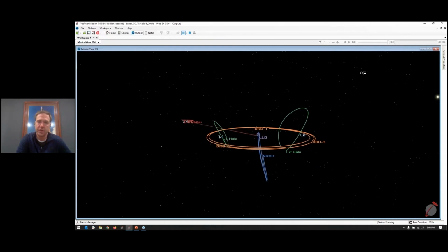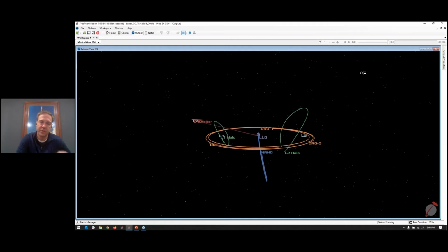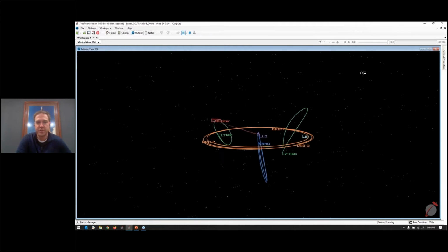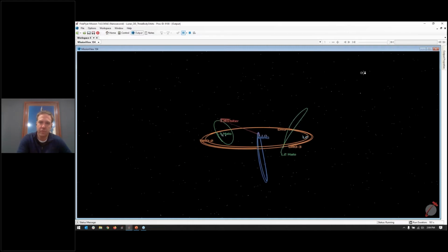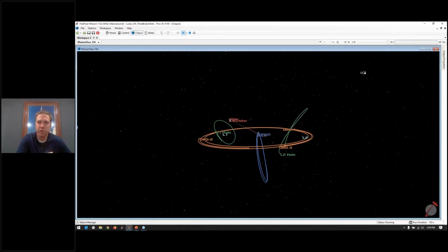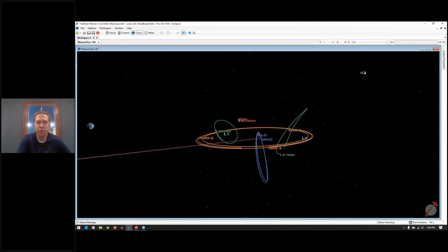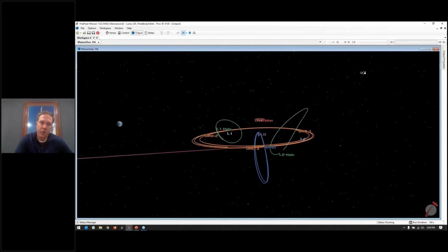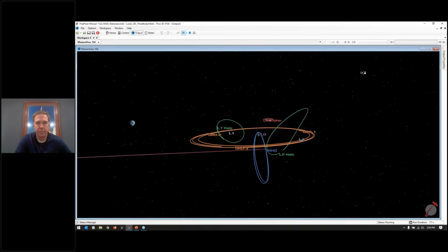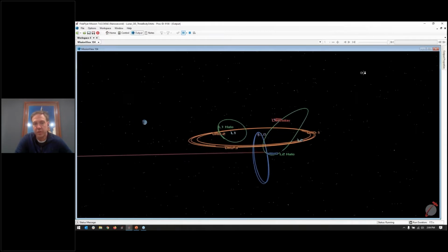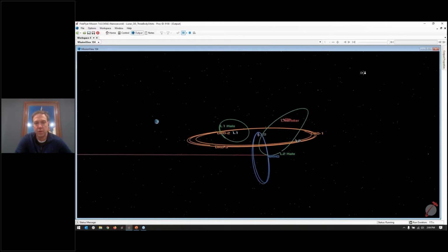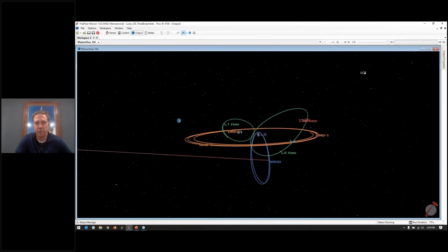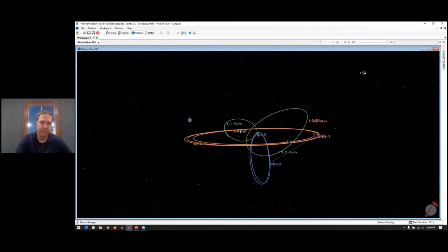As I get into the mission design portion of the talk, one thing I want to mention is that for all of the orbits in this, except for obviously the low lunar orbit, which is pretty simple, and the gateway orbit that I'm showing, I used FreeFlyer's rotating pulsating coordinate system to target all of the DROs, all of the halos, and even the L4, L5 orbiters.